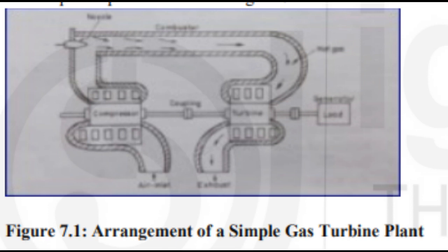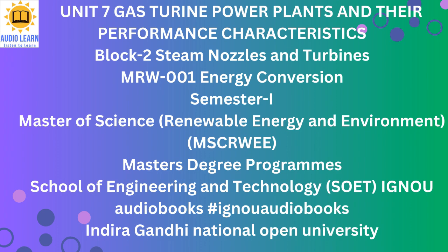A stage is formed by the combination of a row of fixed and a row of moving blades. The power of the turbine depends upon the size, shape, and the speed of the blades used. Multistaging is employed to increase the power output of the turbine by placing additional sets of fixed and moving blades in series. The moving blades may be mounted on one or more wheels or on a drum, and the assembly is called a rotor. For high-speed rotors, solid wheels are employed as a hollow construction weakens the rotor against centrifugal stresses. The rotor may be mounted on a shaft or may be integral with it.